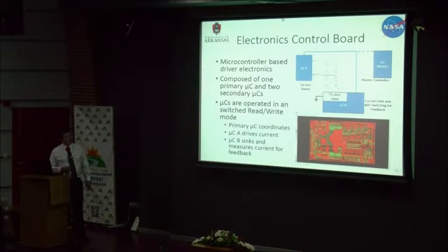It's a microcontroller-based driver system. So we have a master microcontroller. This is a schematic representation of the solid-state gas generator. And then we have a driver microcontroller and a sync microcontroller. The sync will also measure current through feedback, or before feedback, and the master controller will coordinate these things. So we'll operate in a switch mode. We'll write voltage outputs, and we'll read our power readings and current values and incorporate that with feedback.